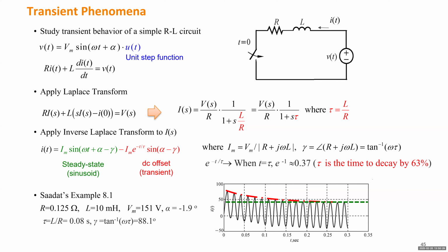Okay, so what do we learn from this slide? In order to obtain the waveform of the detailed dynamic, you can definitely use the very accurate model to integrate current and voltage, starting from the beginning of the disturbance. You're going to integrate many equations. For each generator, with a cylindrical rotor generator, you have 6 first order differential equations to integrate.